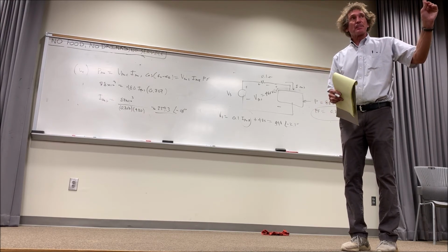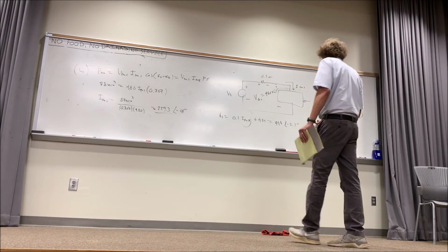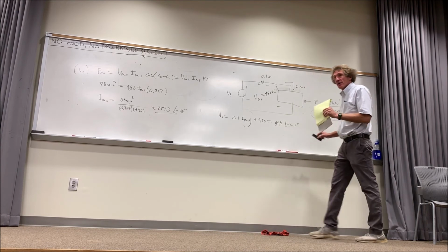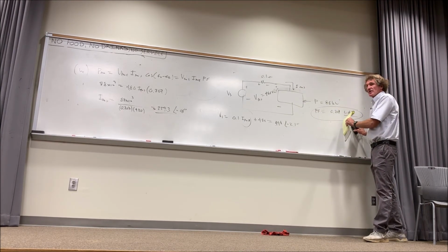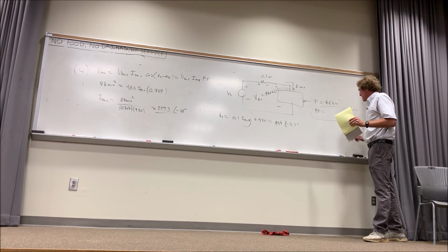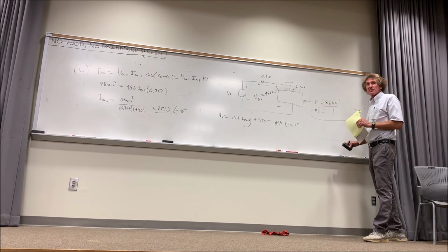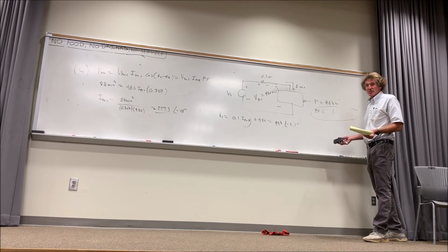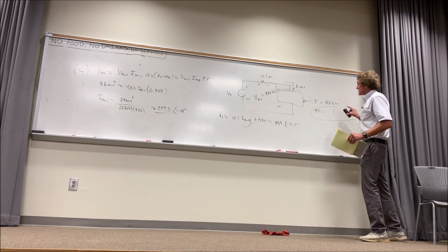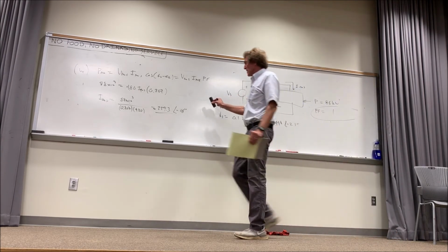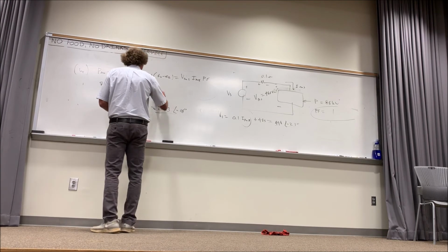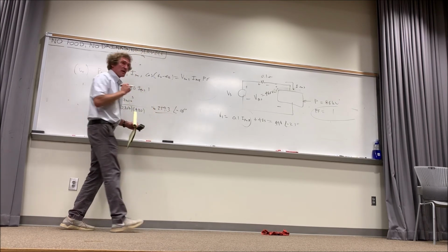And here's why. Let me show you. What happens if the power factor here is not 0.707, but it's perfect, it's 1? All right? If the cosine of theta v minus theta i is 1, that means the difference, theta v to theta i, is 0 degrees. Do you agree with me? Correct? All right, if this is the case, and it's still 88 kilowatts, then over here, we go to 1, right?